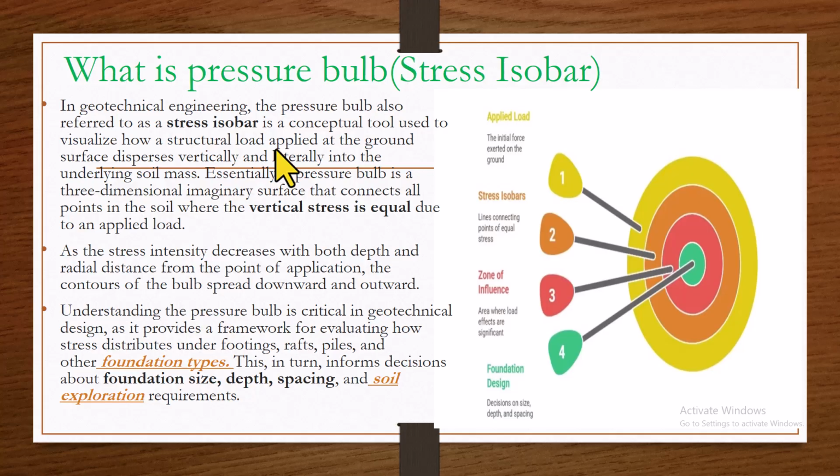No. Soils deeper down will also experience that stress. So once you apply a load, once your footing is there and your building is loaded, and there is a load transfer to the footing, you discover that if you have a footing at 2 meters, from that 2 meters down to about 5 or 6 meters, we still feel the effect of the applied load.